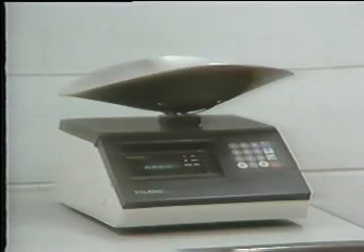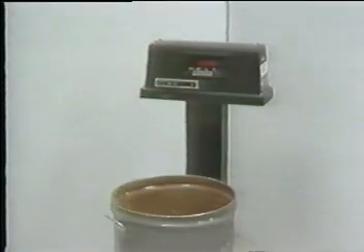For this test, you will need, for fine aggregate, a balance or scale readable and accurate to 1/10 of a gram or 1/10% of the test load, whichever is greater. For coarse aggregate, or mixtures of fine and coarse aggregate, a balance or scale readable and accurate to 5/10 of a gram or 1/10% of the test load, whichever is greater.